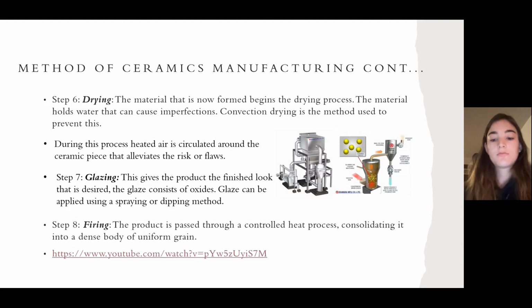First, the raw material is fed into a grinder and pulverized into smaller, more manageable clay powder. The clay powder is combined with quartz, feldspar, and water in a mixer for 15 hours. The refining process continues as the clay slurry is fed into the molding tubes and cast into long clay logs, which are cut into specific portions.